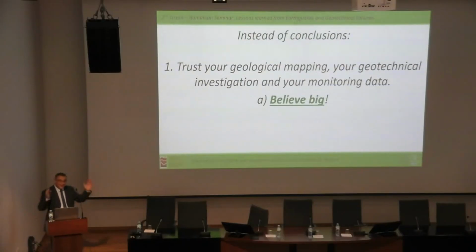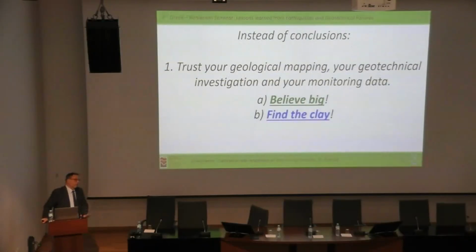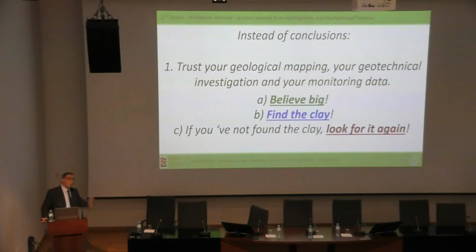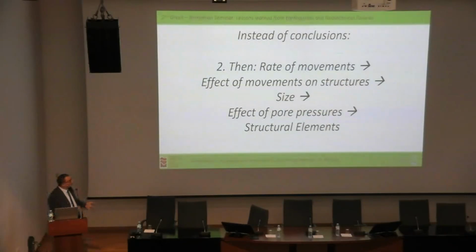Find the bloody clay. Period. Find the clay. And if you didn't find your clay, go back and look for it again. No landslide that respects itself has nothing to do with clays. All landslides that respect themselves are seriously affected by clays. And once we do this, try by using something like the logical diagrams I showed you before. Consider the rate of movements, the effect of movements on structures, the size, the effect of pore pressures and their decrease, and finally, anything that you can do with structural elements.